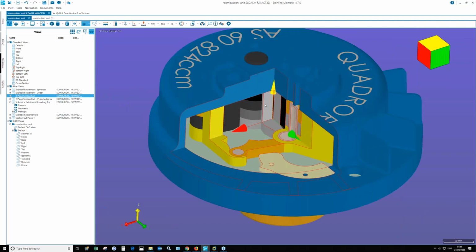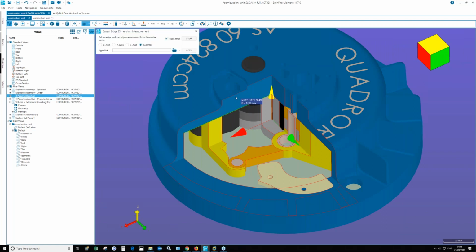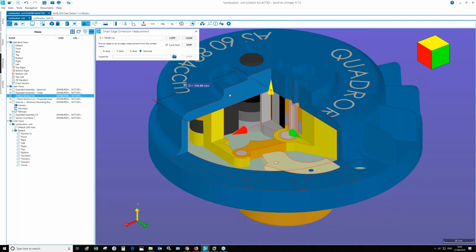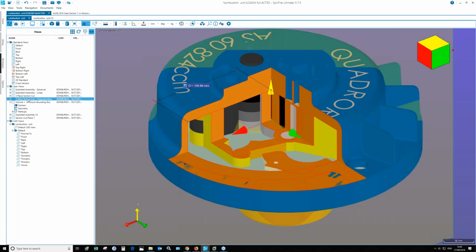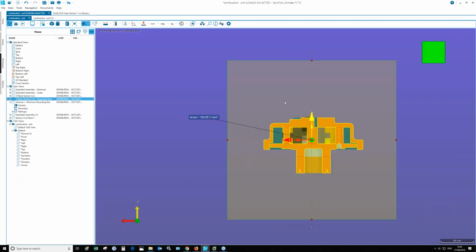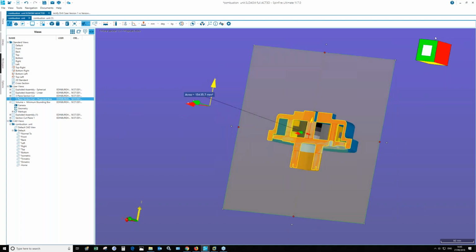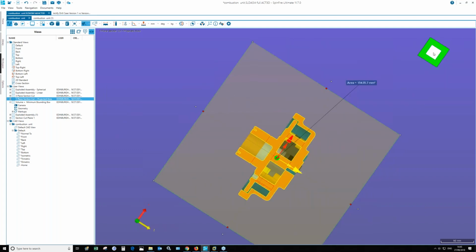At this point, I can start again using the various different measurements within that file that I've done a section cut on, and that will be saved. Those measurements, those actions that I take against the file within that user view, will be saved in that user view. So you can see here an earlier projection area calculation I did. I've got it at a certain rotation. I can change that rotation using the navigation cube. I can click the cube to rotate the model in this way.